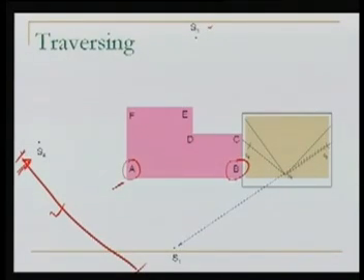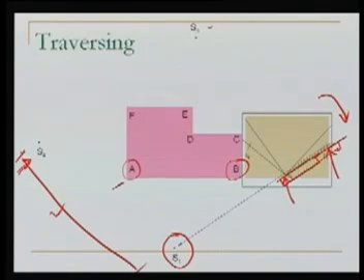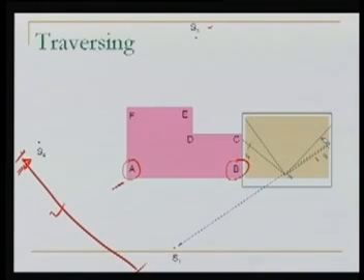Well, at this S2, we will orient our table by the backsighting. Backsighting means we are keeping the alidade at S2, and we are keeping it in such a way that the straight edge of the alidade passes through S1. Or the other way around, I can say we keep the alidade in such a way that its straight edge is passing through S1 and S2. Then we rotate our table at this point in such a way that S1 is bisected. Once that is done, the meaning is we have oriented our table. So the table is oriented now.